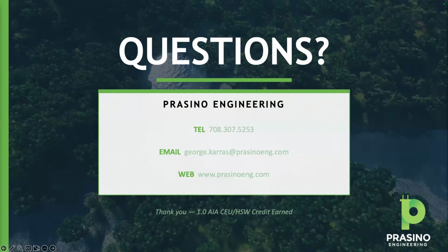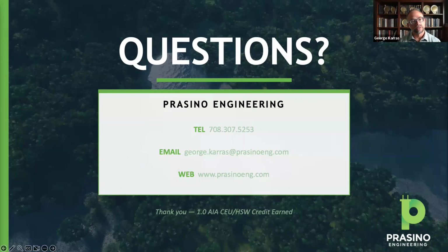We have a question from Jason in the chat. What has been your enforcement experience with the new envelope requirements? Great question, Jason. Truth be told, and I alluded to this a little bit, ROEs and AHJs are still learning the code. We haven't had a tremendous amount of AHJs asking for certain documentation. But it is obviously in the best interest of the design professional to perform everything per the letter of the code. So we have been providing building pressure envelope testing and providing that information to the ROE or the AHJ, but no one's been coming and asking for it, truth be told.